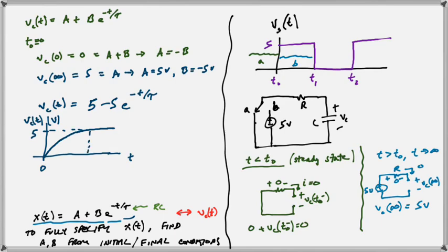And what we're going to say is, at some time, 5 tau, you could do the math, but at that time 5 tau, VC of t is approximately its asymptotic value, so it's 5. It actually reaches 99% of the asymptotic value by that time. So that's what we've got going on: when the voltage input goes from 0 to 5, this capacitor rises like this, it's charging up to 5 volts, and it has an exponential rise.